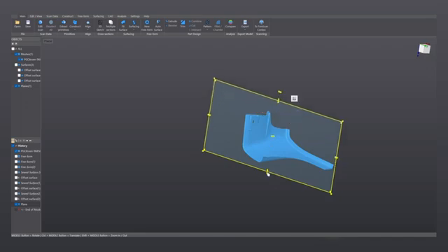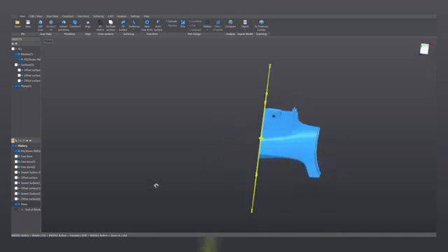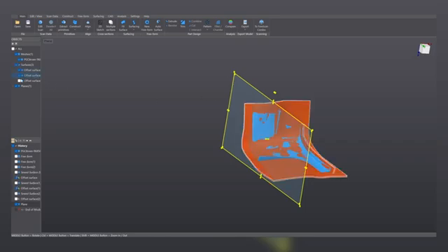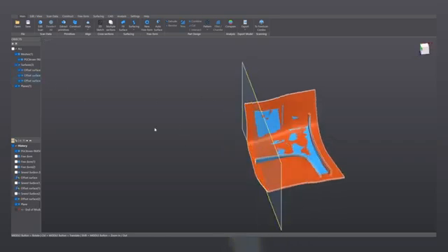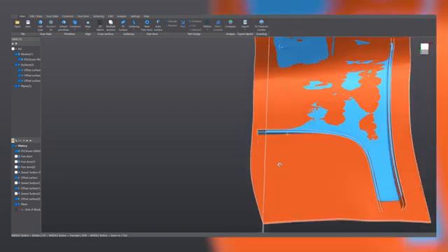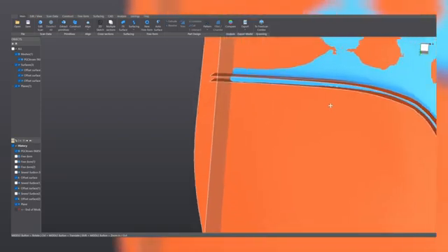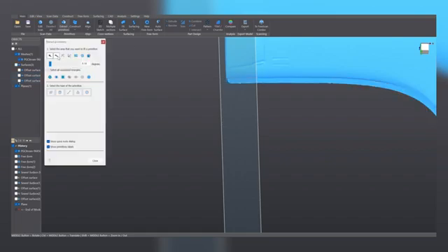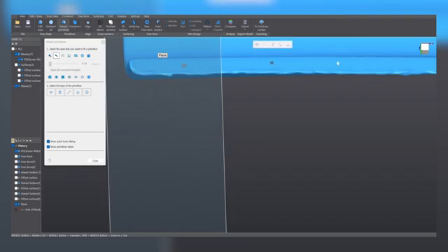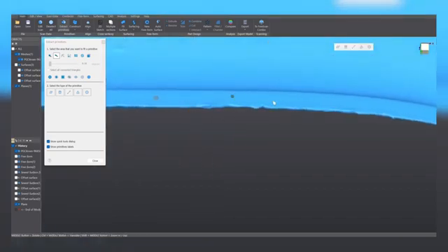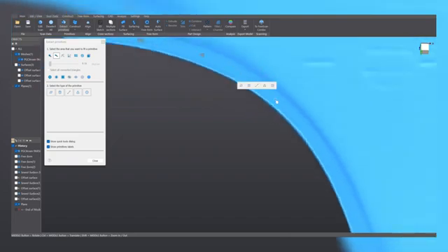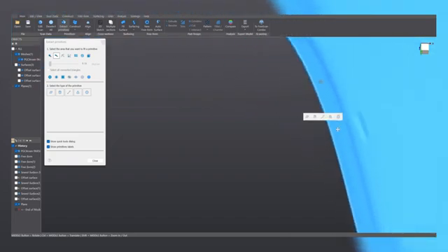Right? We have our nice plane here cutting actually my surfaces. Nice. Okay, what else do we need? We need another plane here. This one, we will extract it. We simply select some triangles corresponding to this face, and we are gonna best fit a plane there.